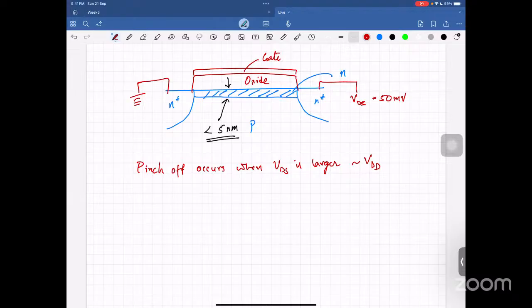How will the voltage be distributed across this? It will depend on VDS also, right, sir? Yes, correct. So what we are saying is this is almost like a metal, a large, high doping region. There's a slightly lower amount of doping here, whatever, the inversion charge here. But there is a drop of VDS across this, isn't it?